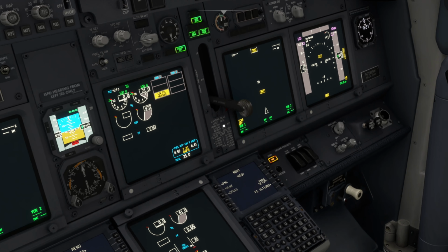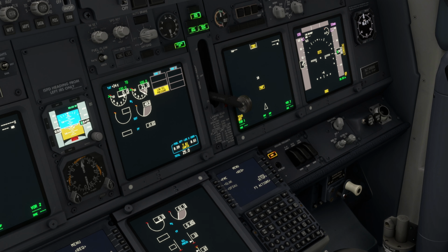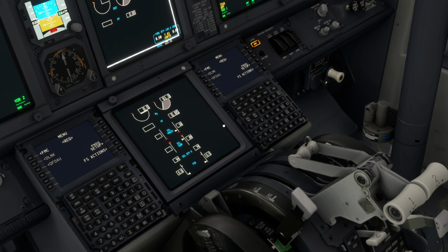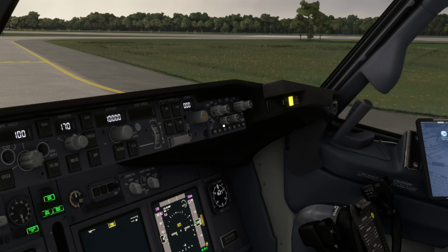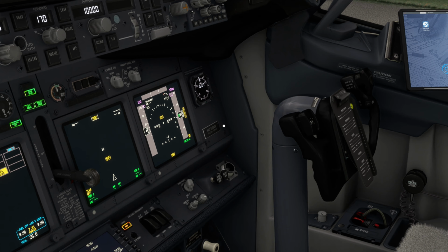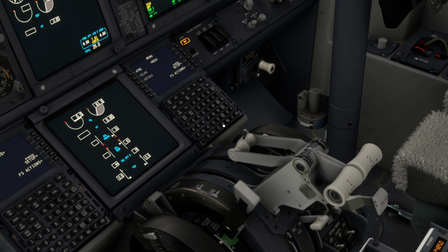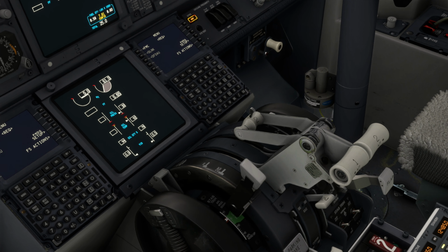We don't see flaps, slats, or spoilers deployed on the accident video here on Jeju Air Flight 2216. That indicates to me a complete hydraulic system failure. Similarly, we do not see symmetrical thrust reverse deployment on Jeju Air Flight 2216. The thrust reversers, as we talked about earlier, are the panels of the engine nacelles aft that will deploy rearward longitudinally when the weight on wheel sensors detect that the airplane has touched down on the runway in the main gear, and then they will redirect the engine thrust down and forward.